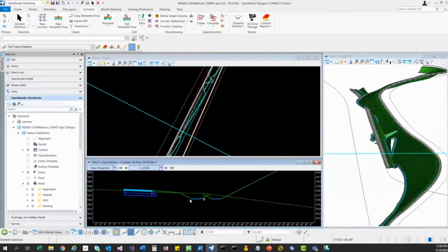Right now, obviously, I don't really want these two ditches overlapping each other, right? What if I really only want one ditch? Okay, how do I do that, and how do I do that so that I don't lose my standard slopes? Granted, I could definitely point control both ditches to a common point, but then I'm going to lose this slope value that I want to maintain. So the way you've got to first think about it is not having two ditches, but having one corridor target another corridor.